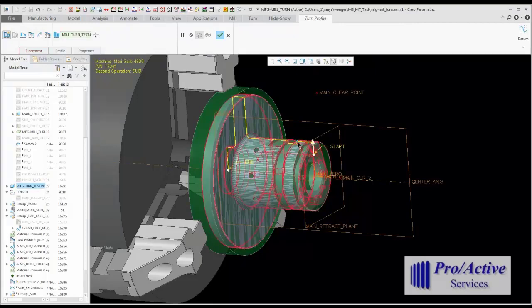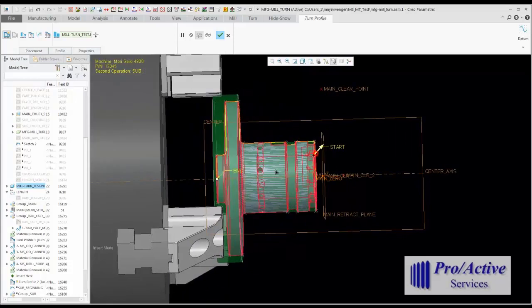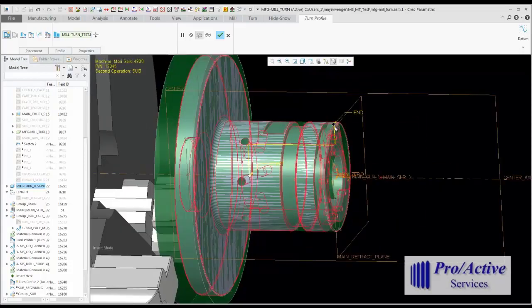Select the reference part, drag this down to the center, and I can set this right here to the end point. And if I want to, as far as the direction, I could change it at any time. So there's my ID. Actually, let's move this down here. That is going to be the area I'd like to bore out.